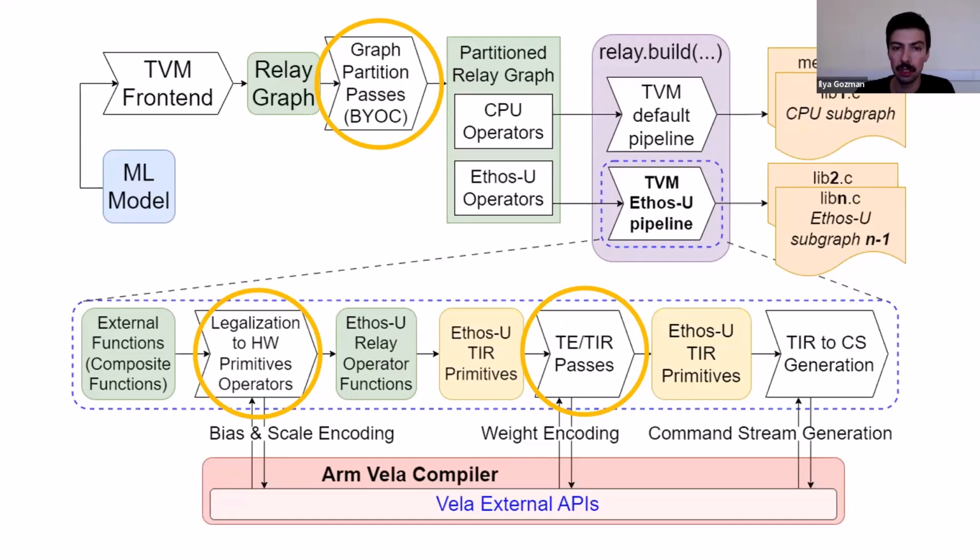The next stage will allocate such functions to Ethos-U NPU hardware primitive operations. These operations are defined as tensor expressions, closely describing the compute of each primitive operation that the hardware can natively execute, in their own Relay operators. They represent a pattern of conventional Relay operations that are executed atomically in the hardware.